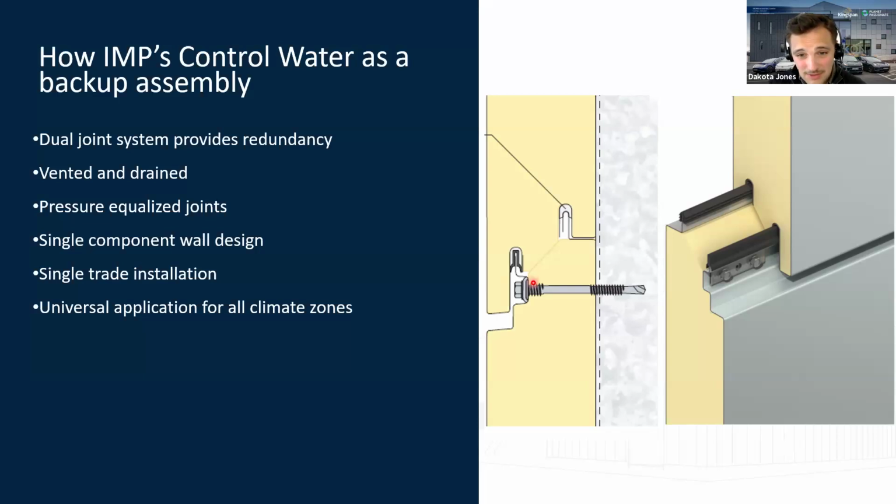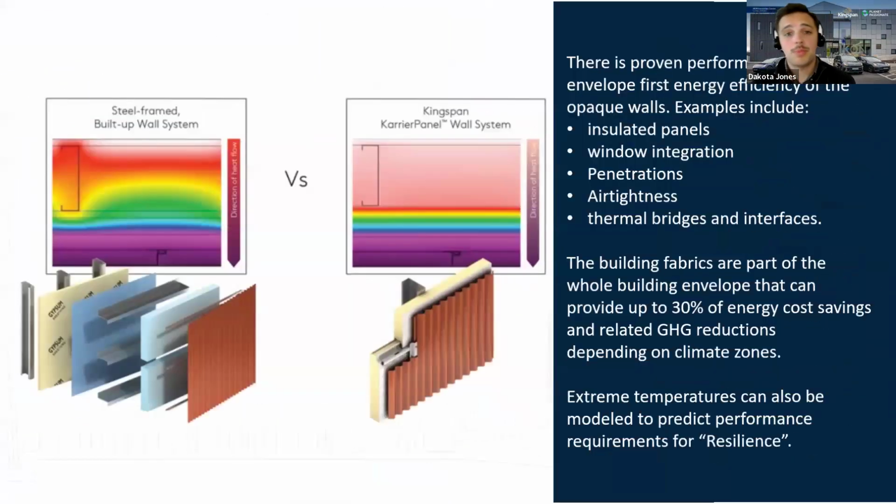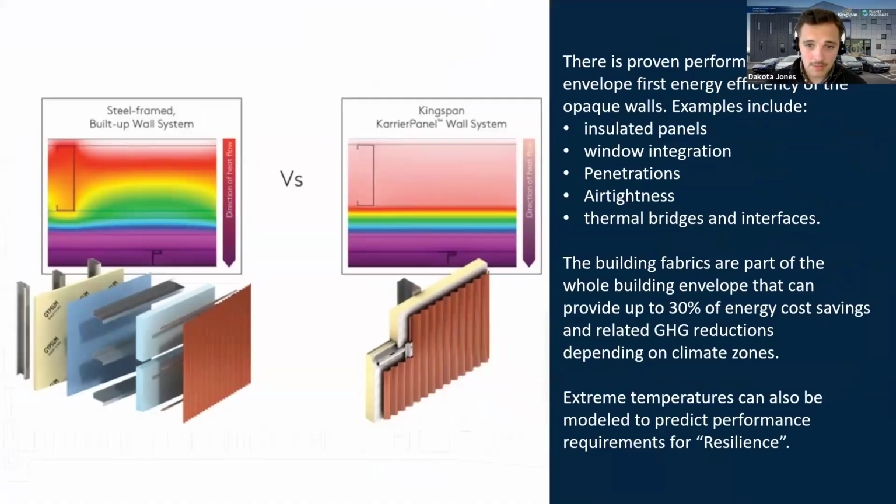The steel itself is galvanized, meaning that fasteners that do pass through it make a nice snug connection, self-sealing, right? And so what we have is a system that blocks air infiltration and vapor by association. Thermal insulation blocks our thermal loads from getting in there. And then, of course, water infiltration, because it's steel, just runs right off the side, right? So what we have is a system that can work in every single climate zone, all in one, mounted directly to studs.